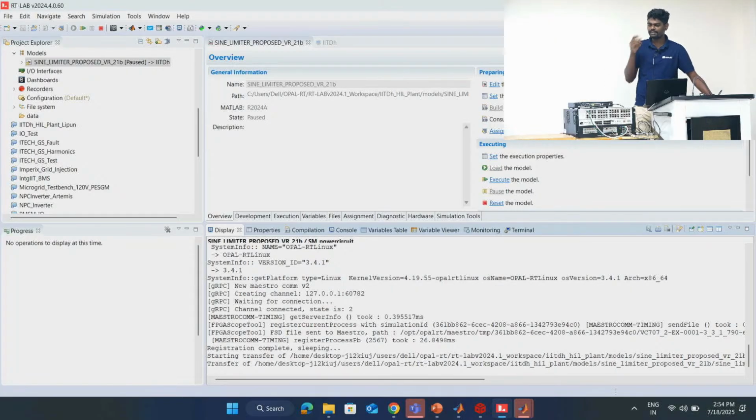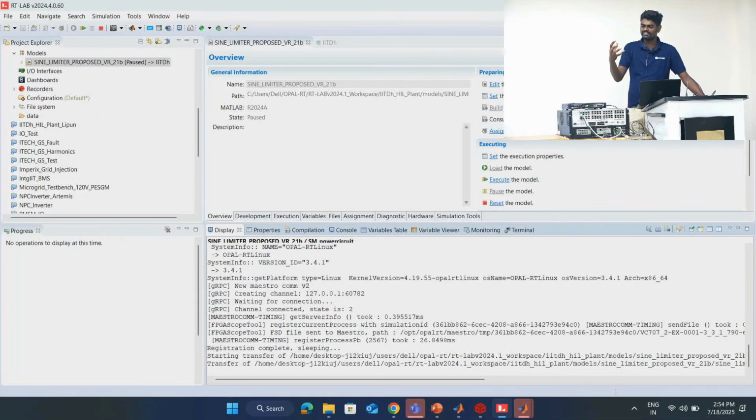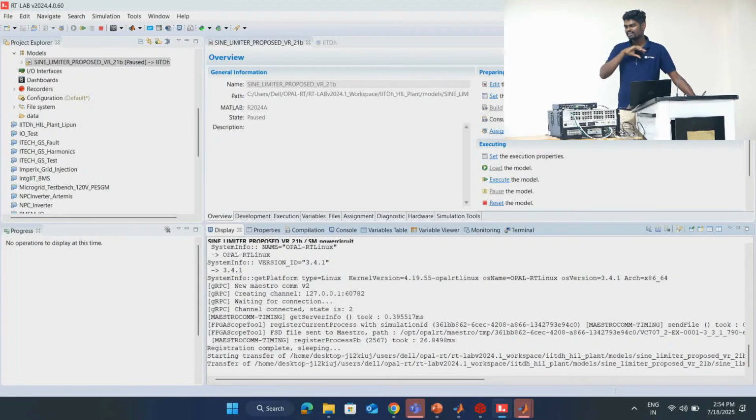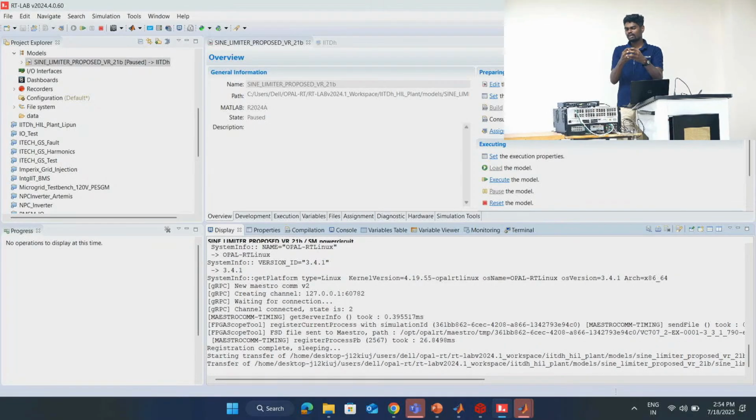Power level will come into the picture when, let us say you have an inverter and you want to link that inverter with a simulated motor, and whatever changes you see on the simulated motor, you should see the change of that motor at power level with the inverter. So these kinds of simulations will need a power amplifier in between.